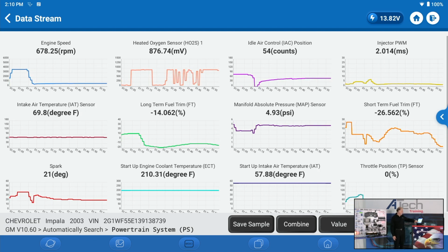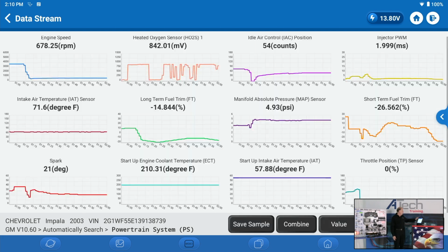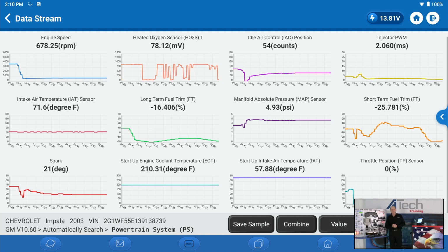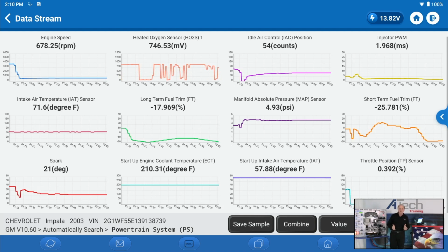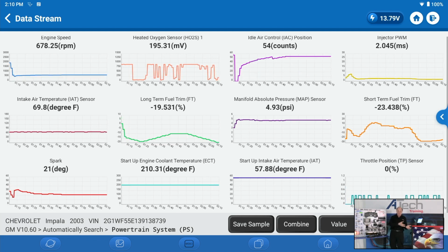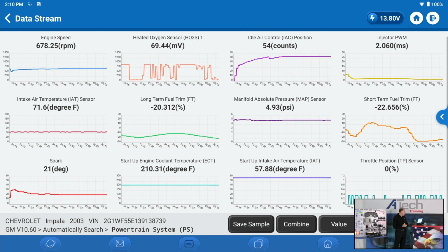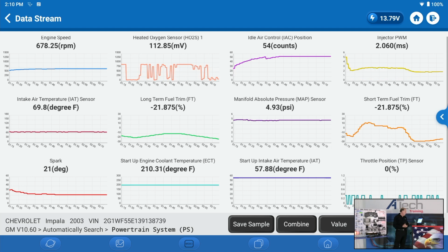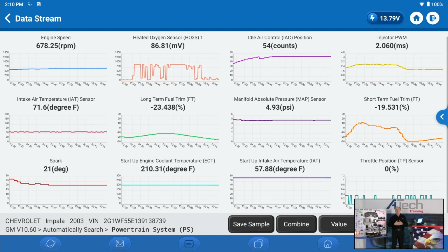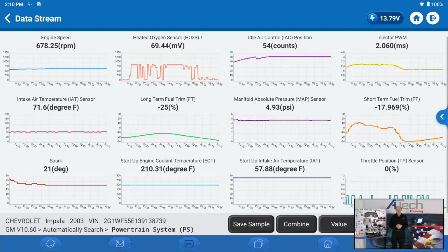So if I'm looking at the process, guys, you can actually pick out one. We're just showing you some of the outputs you need to look at. The injector pulse width, if everything's working properly, should increase and it should follow the throttle, which it did. We're looking at the mass airflow sensor, that's an input. Spark advance should follow the throttle, which it does. So we know we've got good information.